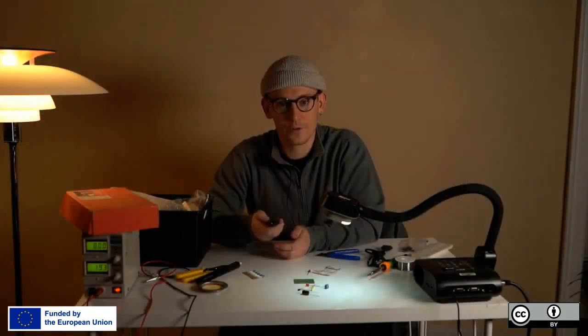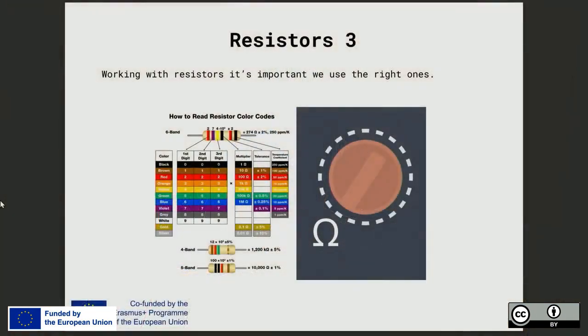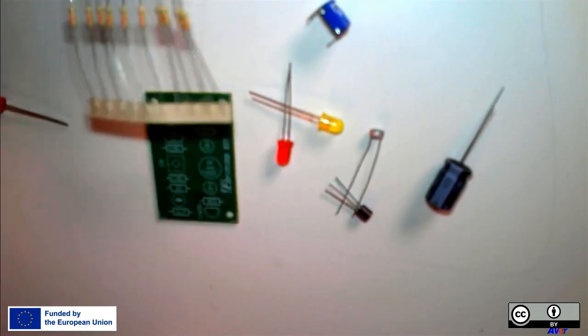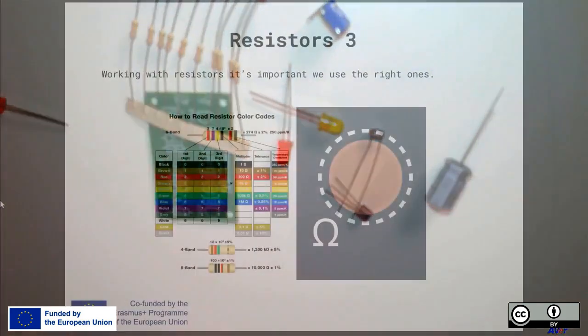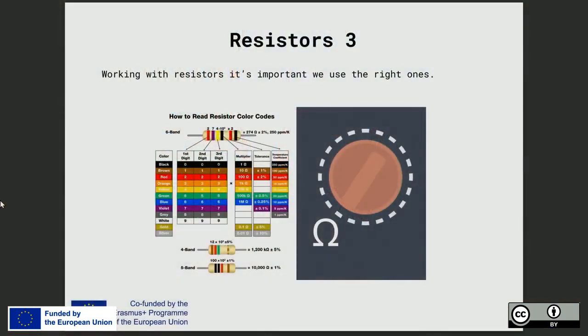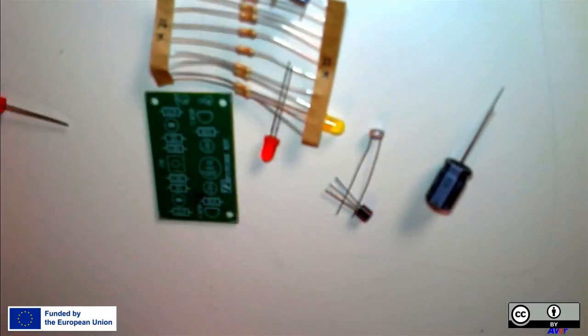And as you might have seen, some of these have, or all of them have, color codes reflecting some value of resistance. You can use these to determine how much value it has. I more often than not just use a voltmeter to check them, just put it on the resistance symbol and measure it. I find that to be more accurate and easy, and then I just try to keep them in semi-order. With projects like this, I try to keep them together with the other 12Ks, but when you mess it up, and you eventually will, it is nice to just kind of check it.